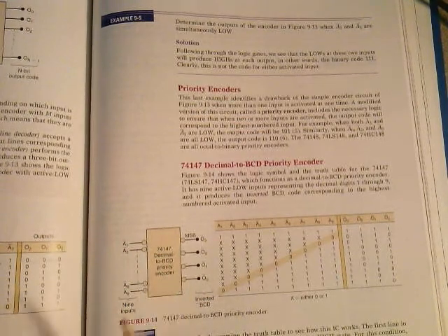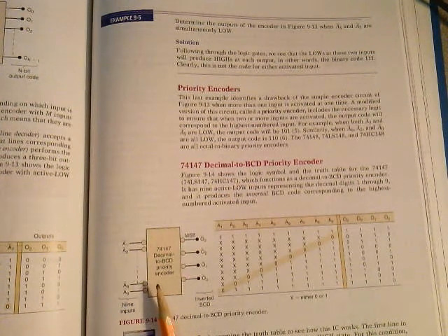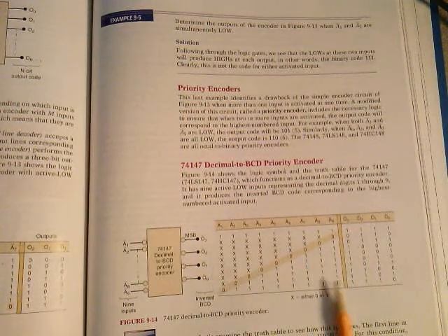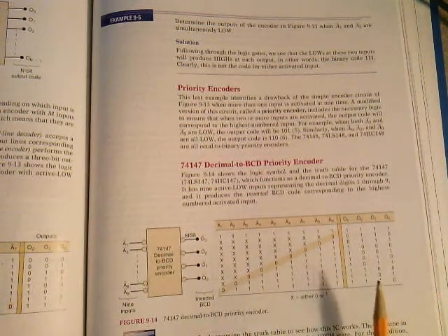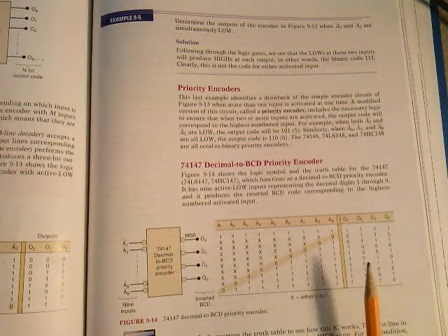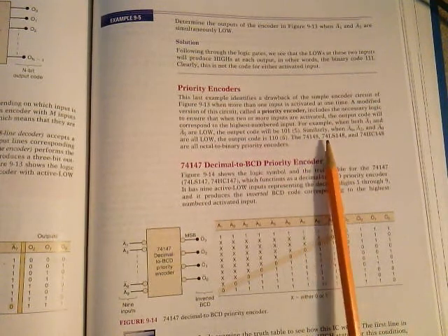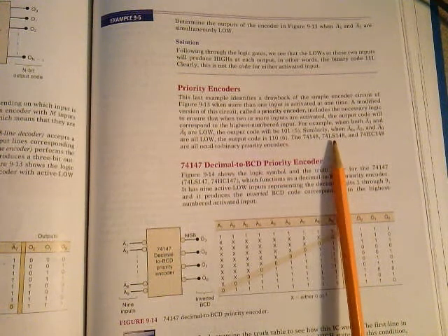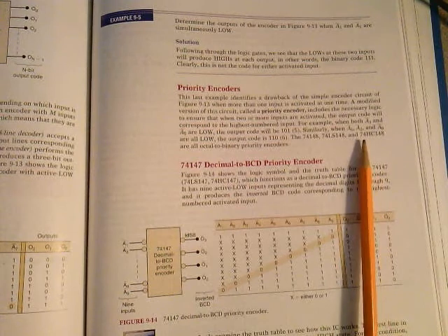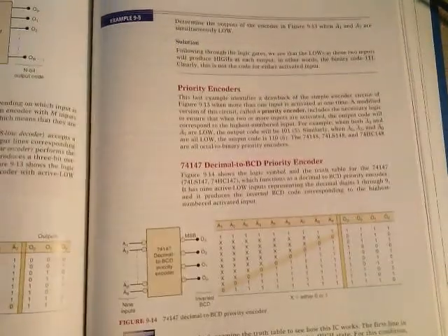So when you purchase these as an integrated circuit, you'll see that in a minute. That priority encoding is taken care of inside the chip. And you can take a look at it here. This is the truth table for that. These come in many different families. It's a standard 74148 priority encoder. It's a low power Schottky if you need low power and high speed, 148. And it's a high speed CMOS if you need high speed and very, very low power CMOS, 148.